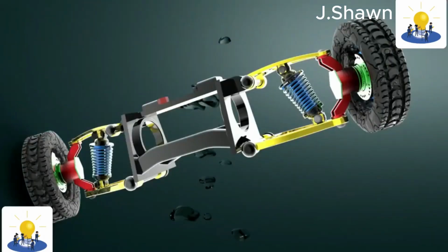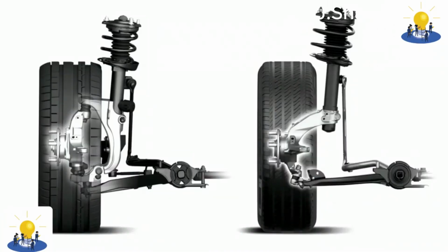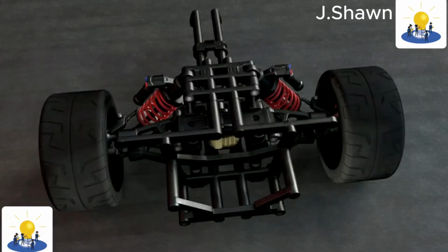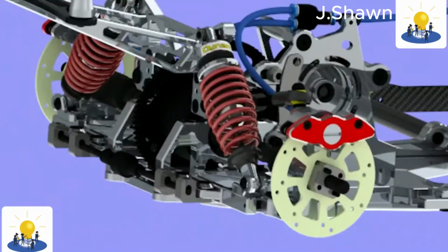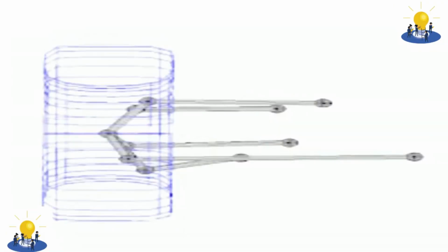For a rear suspension, a pair of joints can be used at both ends of the arm, making them more H-shaped in plan view. Alternatively, a fixed-length drive shaft can perform the function of a wishbone as long as the shape of the other wishbone provides control of the upright. This arrangement has been successfully used in the Jaguar IRS.